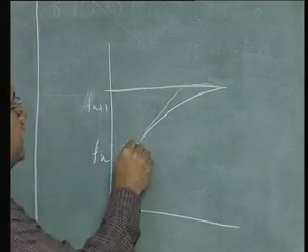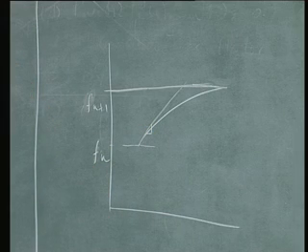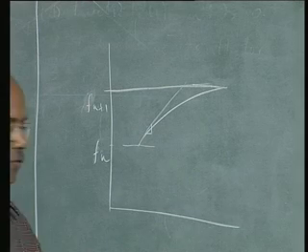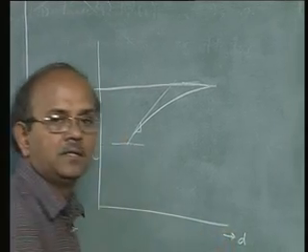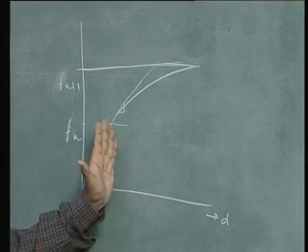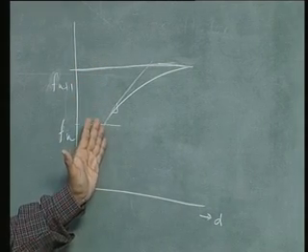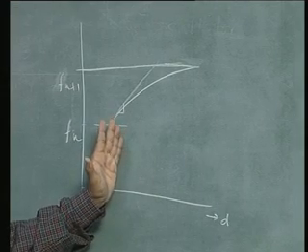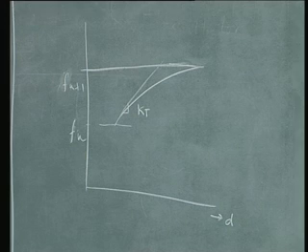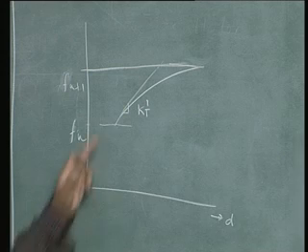I know how to calculate the tangent stiffness Kt at this point. So, tangent stiffness is nothing but, what is it? Dou P by dou u, which in this case happens to be nothing but the slope of this curve. So, the initial slope of the curve at the start of my iterations, or at the beginning of my journey towards n plus 1, is very well known. So, that is the slope of the curve. Let me call this Kt, and usually iterations are indexed here at the first iteration level. I know that.